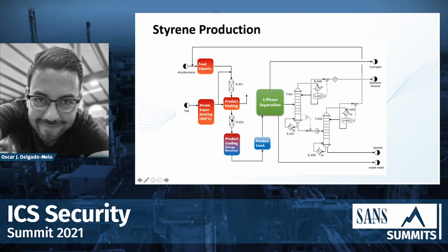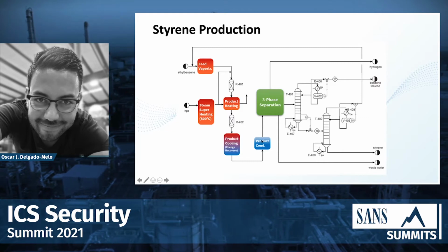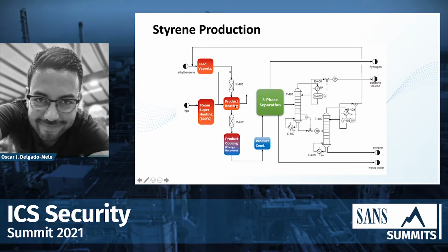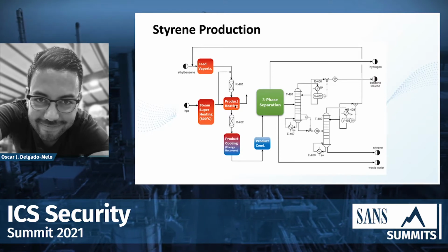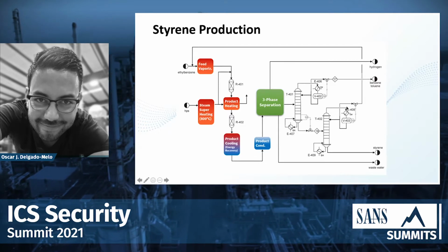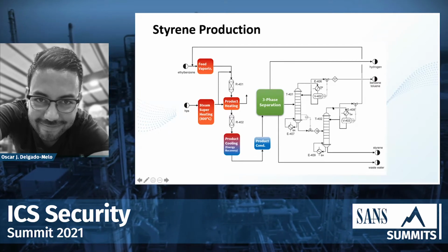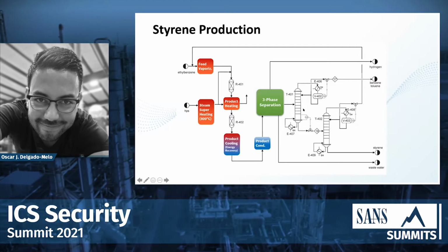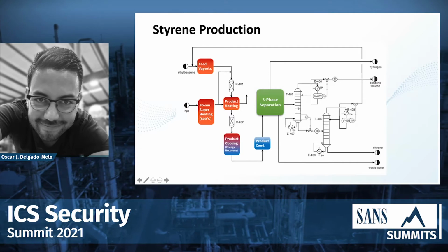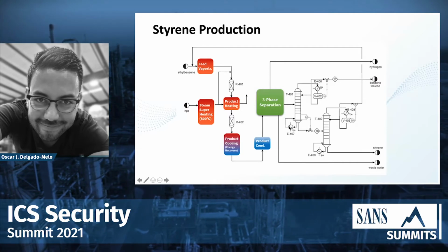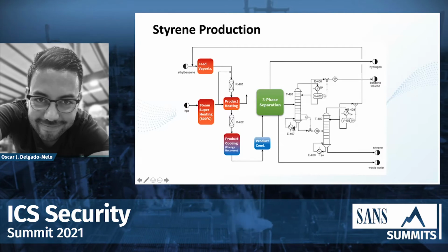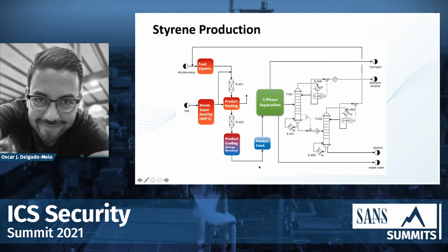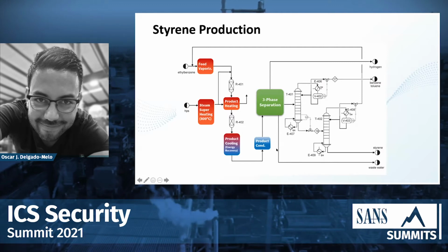In general, I'm putting these two words here just to help me understand what is going on with the process. You will notice that on the bottom right I didn't replace these heat exchangers, and it's just because they are part of a group. When you have these towers, 99% of the time you have a reboiler and a condenser. So instead of using individual blocks, I'm going to replace the whole thing when it's time, okay?